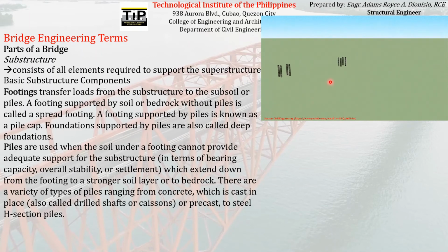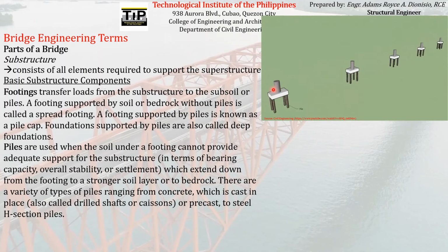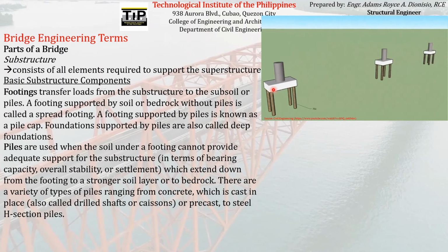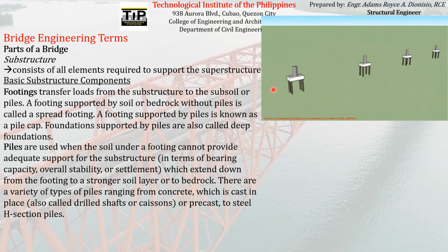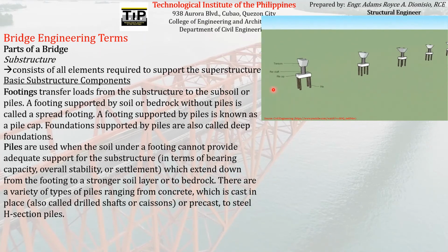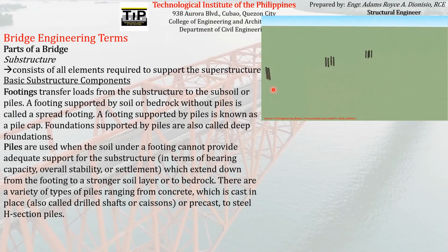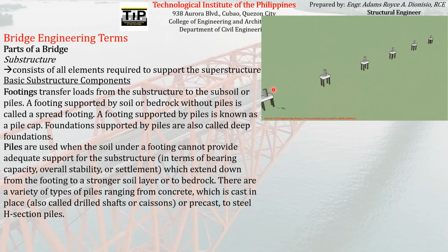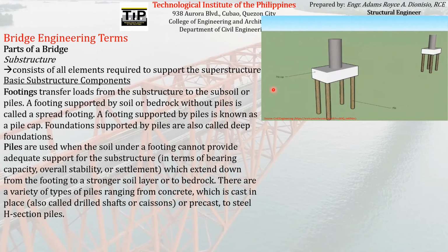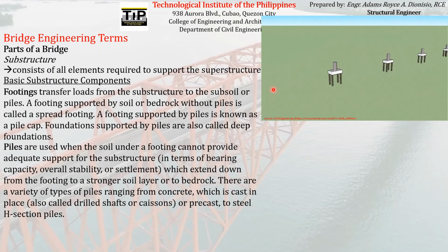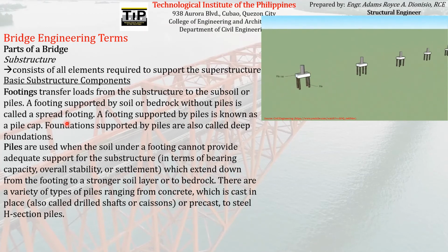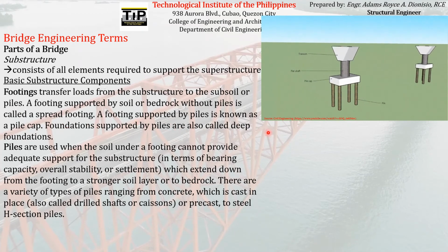We usually use piles as foundations on highway bridge sites that have not-so-good quality of soil, in which case shallow foundations or spread footings are not advantageous to be used.